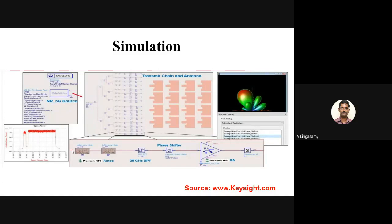Or you can use System View, a software from Keysight. They have these features: system modulation models that can be applied to this RF chain, and then given to the antennas. You can see the amplifier, phase shifters, band pass filters, all those filters, and you can design them all in one particular tool and validate end to end. From the generated signal, passing through the RF transceiver lineup, going to the antenna, and the beam I'm getting, the entire chain can be validated through simulations. This is how it will be done.